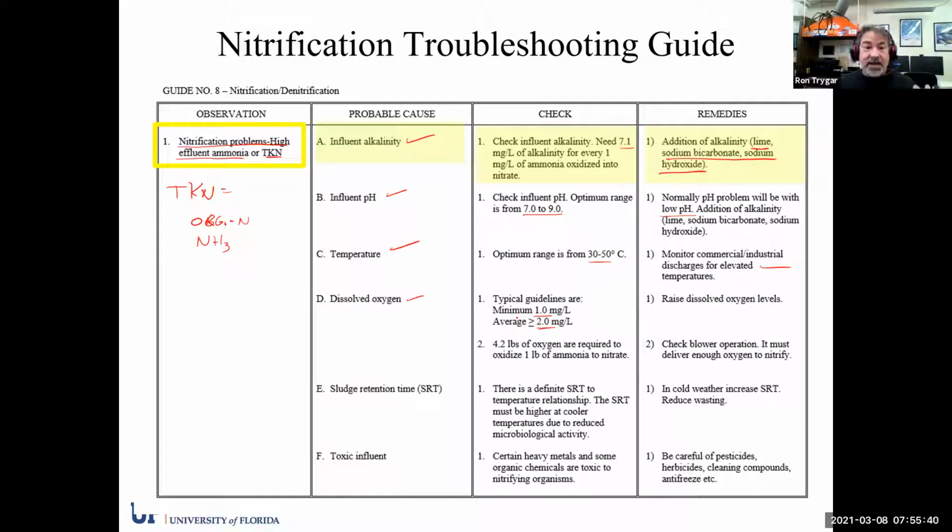And we're saying there that anything over 2 is really not necessary for nitrification. You don't want really less than 1 in most cases to get good, full, efficient nitrification, but that doesn't mean it won't happen if you have less than 1. So typical ranges are around 1 to 2, in that 1 to 1.5 range. If the DO is too low, obviously raise the DO up. If it's too low, let's say around 0.5 all the time, you may limit the amount of nitrification.